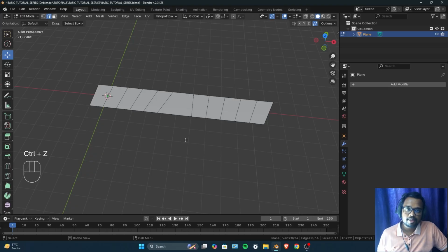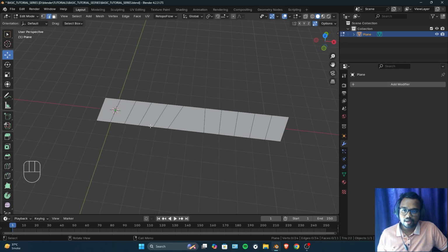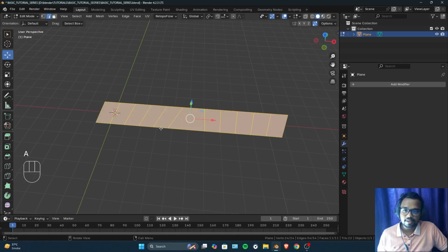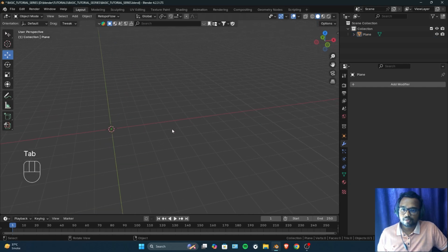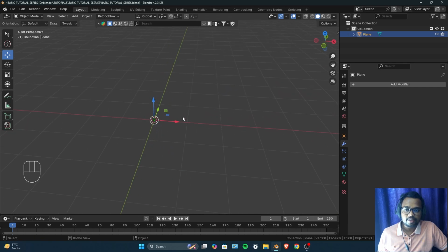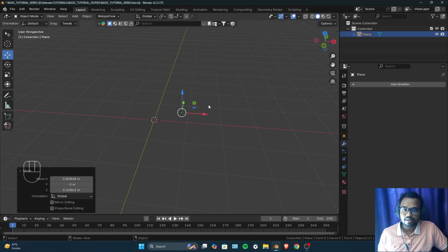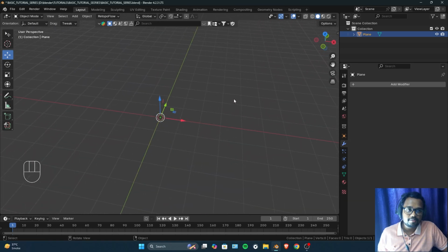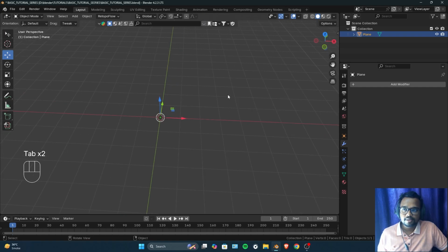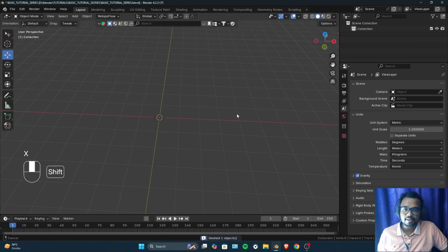Okay, this happens a lot, and I have seen a lot of 3D models with this issue. In edit mode, people just select everything, delete everything, and then get out. Now you'll see that we do have an object, but it is almost nothing. It is just an origin point, like an empty object that has nothing in it. So it is just better to not delete anything. If you want to delete the whole object, just do it in object mode. Just press X and delete it.